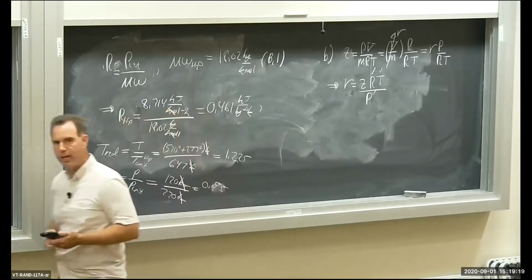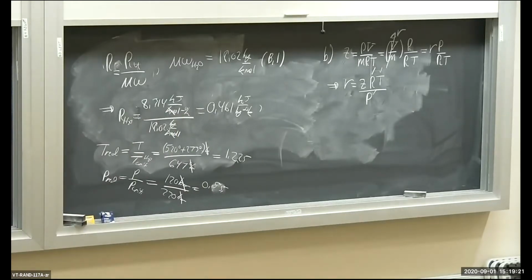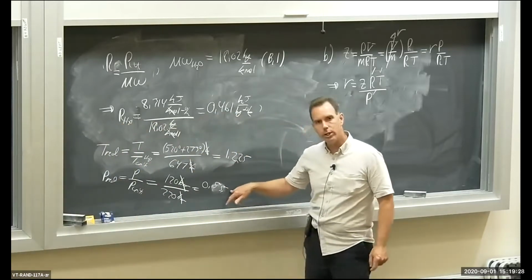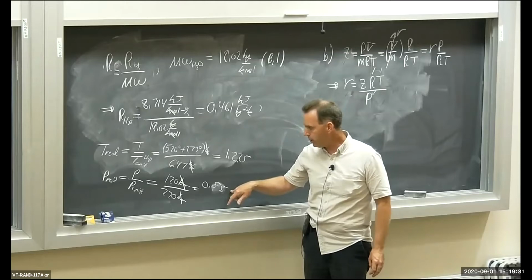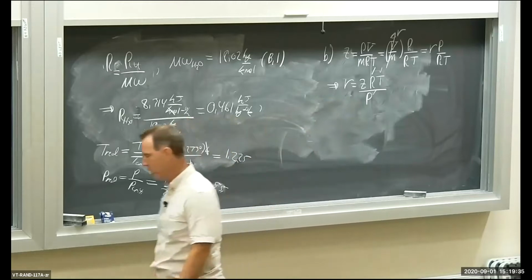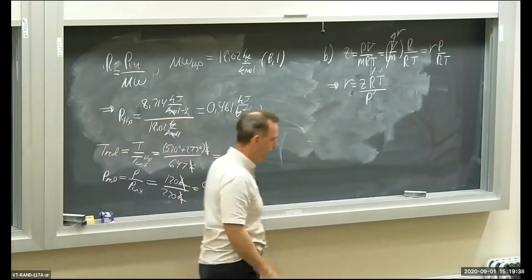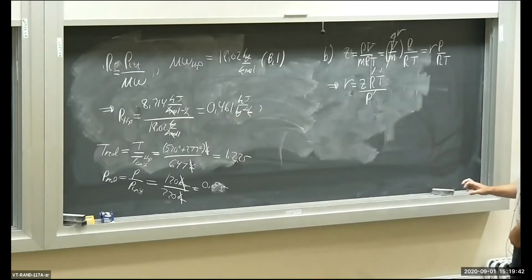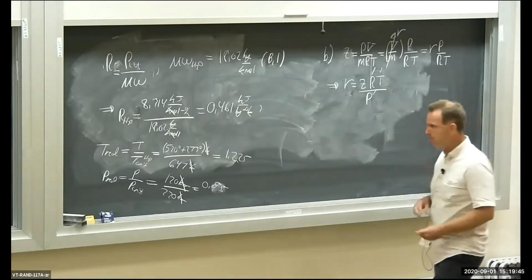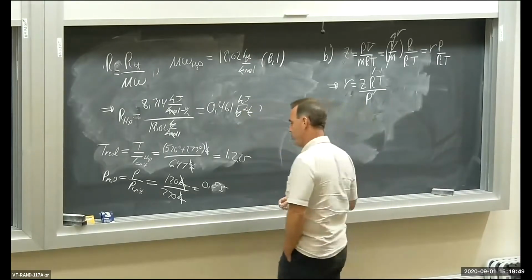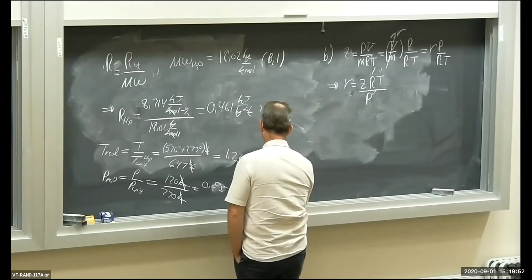By the way, if you're thinking ahead on using the ideal gas law, where Z is approximately equal to 1, we're already in trouble here. Remember the criterion for using the ideal gas law is reduced pressure must be less than 0.2. We're at 0.55, almost 0.6. So clearly for part C, when we calculate specific volume based on the ideal gas law, we're probably not going to get a good result. Okay? In any event, reduced temperature and pressure, 1.2 and 0.5.